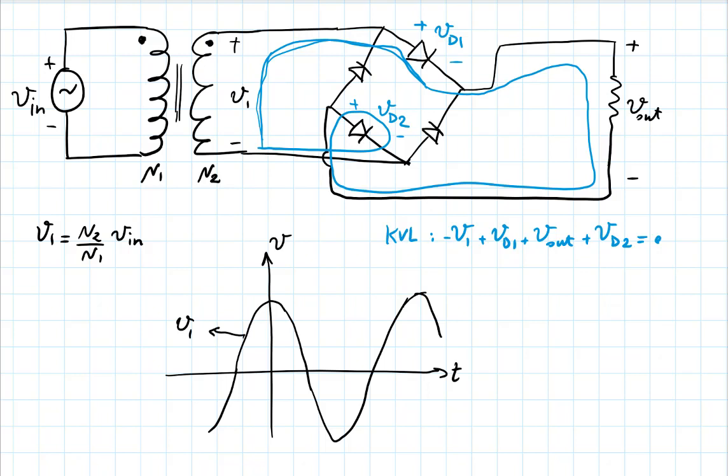Imagine for a second, rather than trying to consider all the 16 possibilities for every value of input voltage, because I've seen it before, let me maybe speed up the way we look at this. Imagine if the input is at a positive point, during the part of the cycle when V1 is positive, would things work out if diodes D1 and D2 were on?